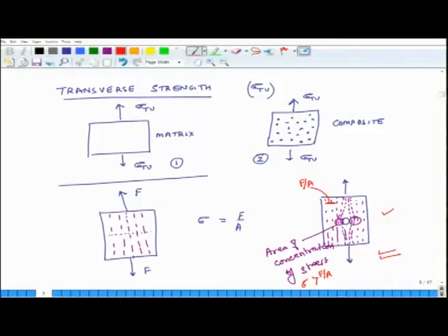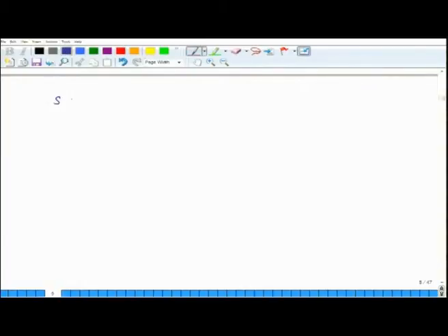So, in general the overall stress around these inclusions, which are nothing but fibers, right, fibers are going in the direction perpendicular to the plane of this board, so stresses around these fibers are significantly higher compared to sigma, this external uniform stress which we are applying. Okay. So, what I mean to say is that when I subject a unidirectional laminate in the transverse direction using a uniformly distributed force, I still have a stress concentration factor SCF,